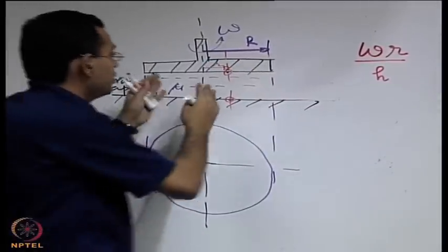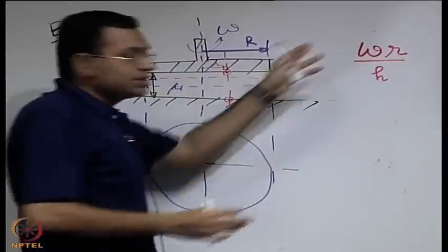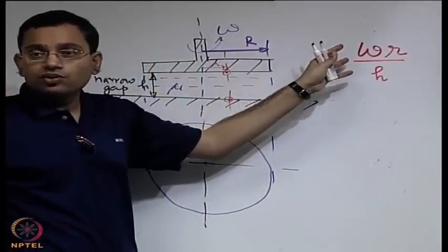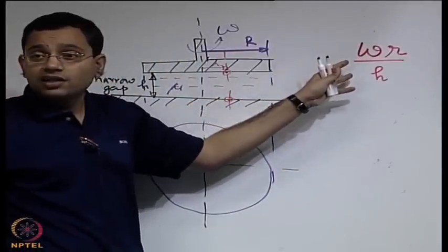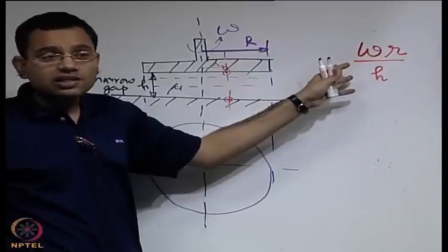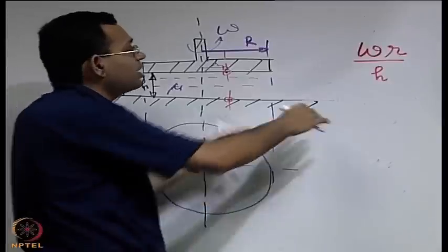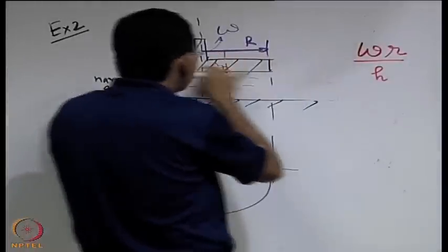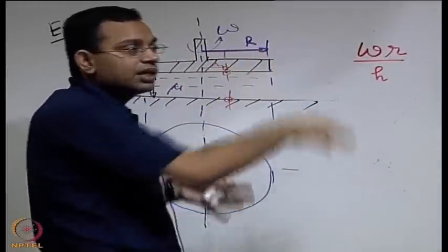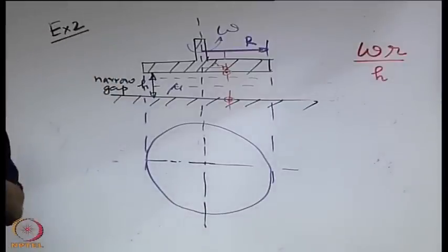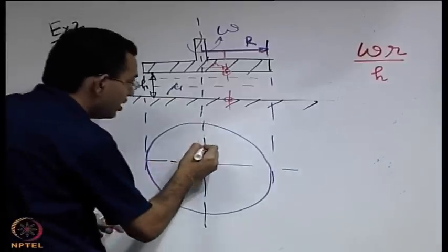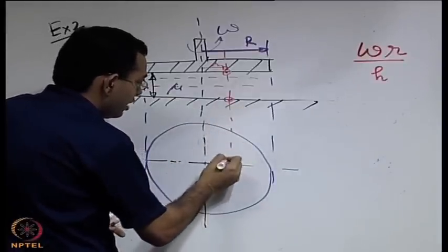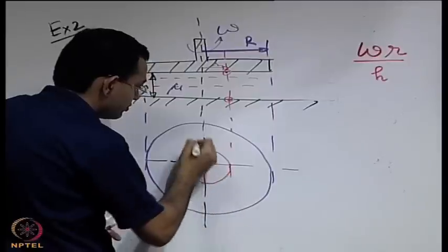So if you take different radial sections, this will be different. If this was a constant, we could have easily calculated the shear stress by multiplying that constant with the total surface area of the plate that is being exposed to the fluid. But now this being a variable, we must take it as summations of constants over small elements, and that is why we have to choose small elements and integrate over those elements.